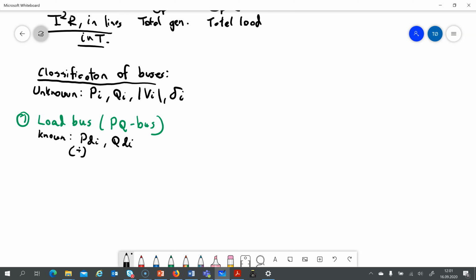So here you specify typically these values for the load in your calculation. Often P_D, the demand of active power, is given, and the Q needs to be found through a cosine function, cosine theta, or power factor PF.